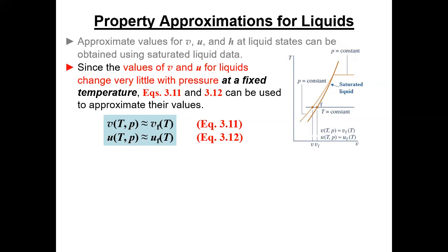Okay, so I got my little calculator up, and I said, okay, I just picked a temperature. I said 300 degrees Fahrenheit. And so the saturation pressure is 67, and the internal energy is 269.5. And the specific volume is 0.01745 out of my calculator, which will be close, but won't exactly match the tables in the back of your book, but it'd be pretty darn close.